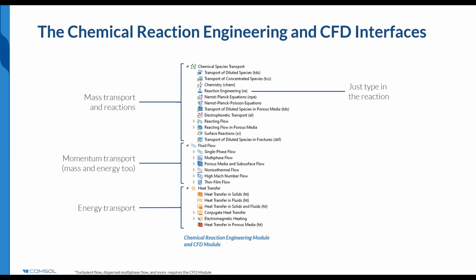So these physics interfaces package up different equations which describe different physical systems or phenomena, and the pre-built physics interfaces help enable easier specification of your physics for each application. They group together the relevant domain and boundary conditions all within a single node. So for instance, here we have the laminar flow interface, and this has nodes for inlet flow conditions of velocity and pressure, or the transport of diluted species interfaces has nodes to describe species flux, concentrations, or reactions, to name a few.